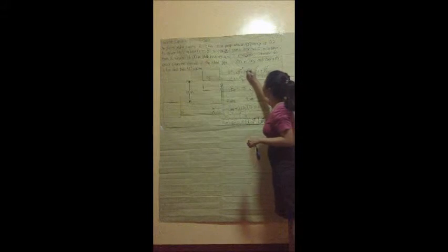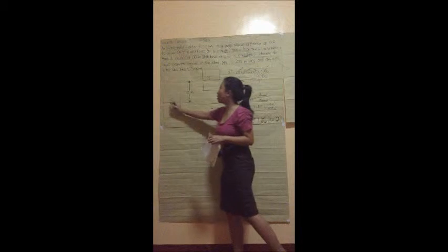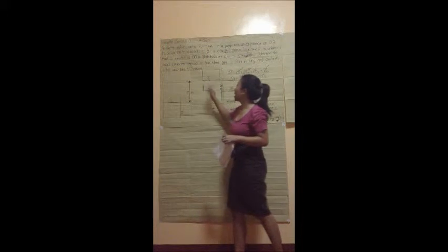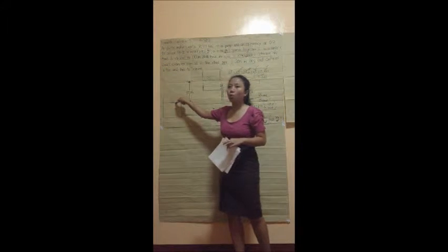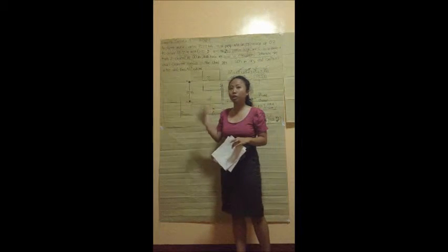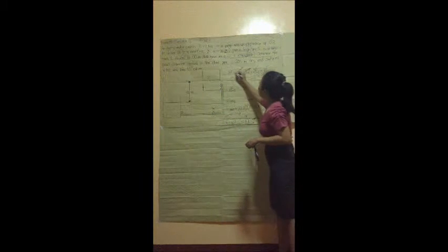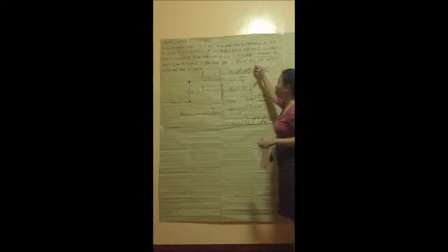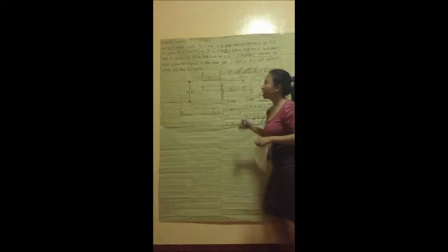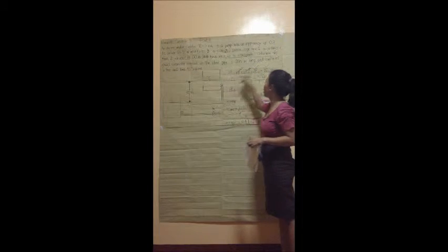Also, we can cancel the change in kinetic energy since our reference points are only the two levels of water, and we can assume that this water has no movement, or it has a velocity of 0 meters per second. So now we're left with the friction losses and the change in potential energy equals the shaft work in the problem. So we should identify the values individually.